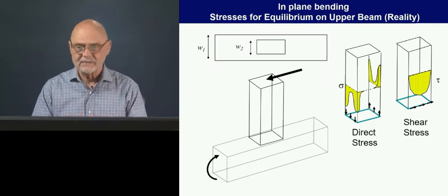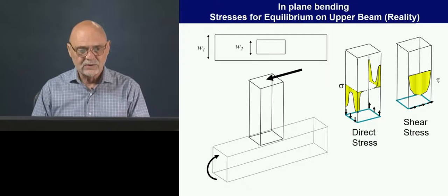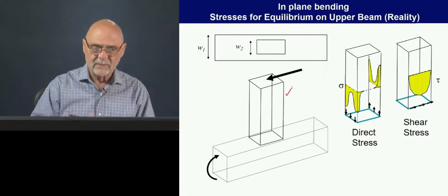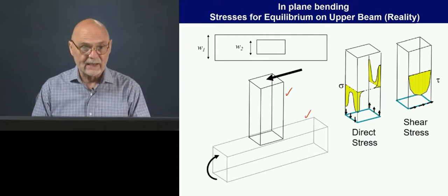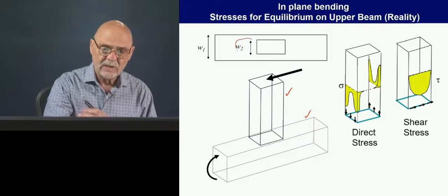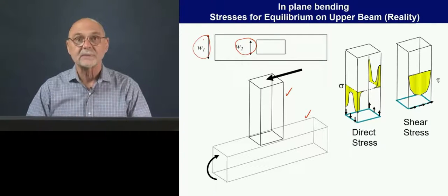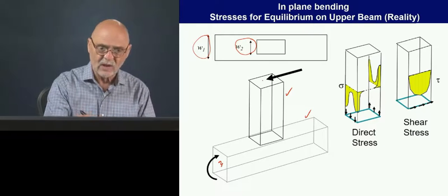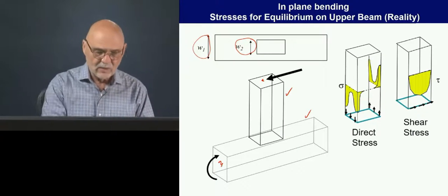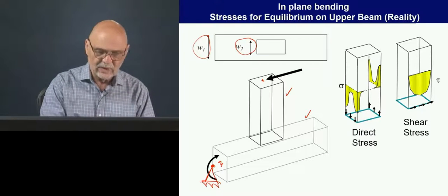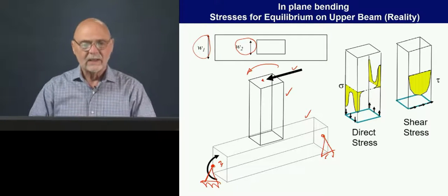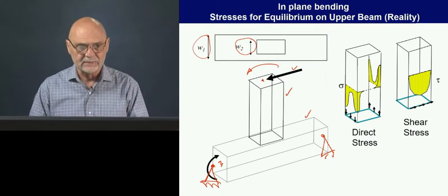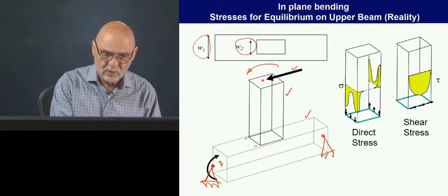So let's simplify the problem a little bit. We're going to consider two beams coming together. This might be a B-pillar, and this might be the rocker section. Initially what we're going to look at is that there's a difference between the width of these two rectangular sections. Again, these are hollow, thin wall sections. We're restraining this here and here, and we're applying a force, or it could be a moment, here at the B-pillar. And there's a little difference here. This width is smaller than this width.